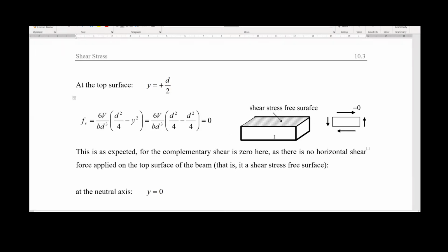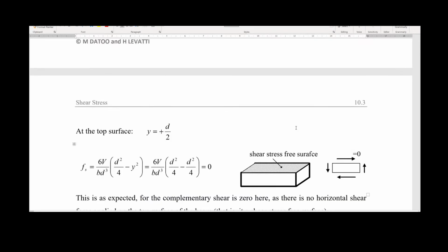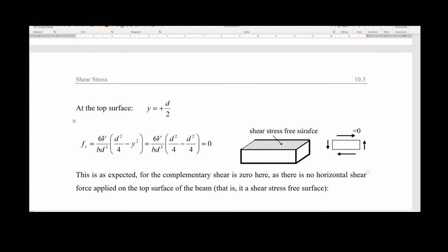So in the neutral plane, we are going to have the maximum shear stresses, not only on the cross section, but in any section defined in the horizontal direction as well. There is a video you will see later in the second part of the lessons where you are going to see these effects explained in a better way, with a graph and a movie, where you will probably understand better what I'm trying to say here.